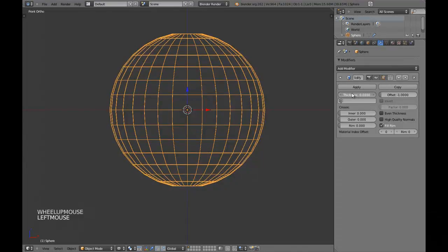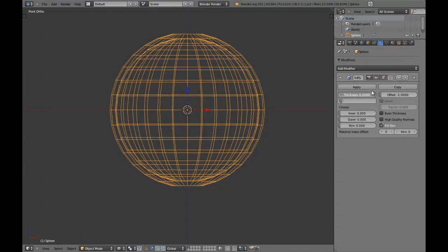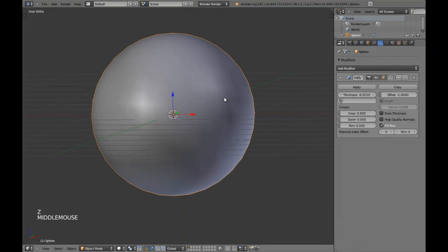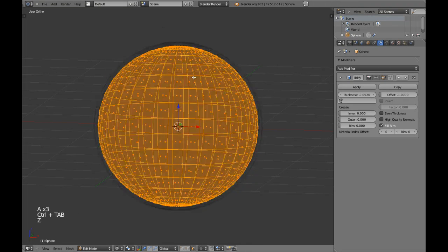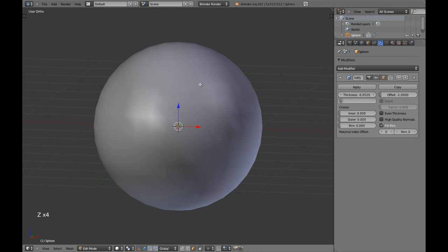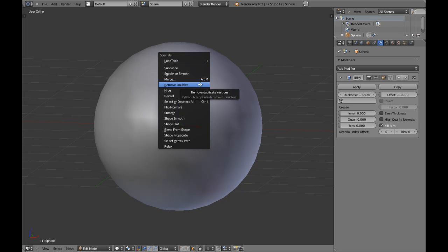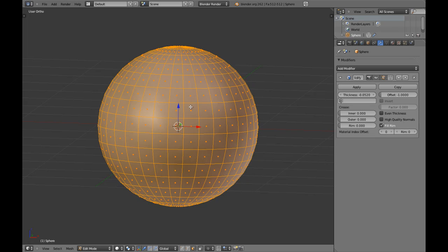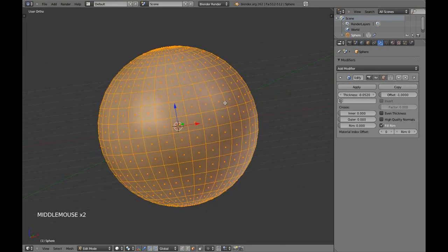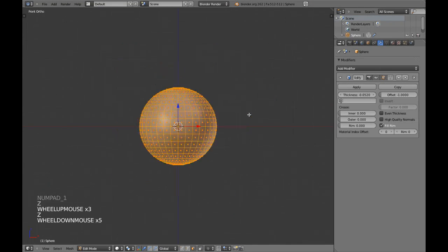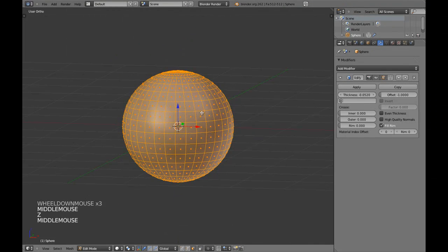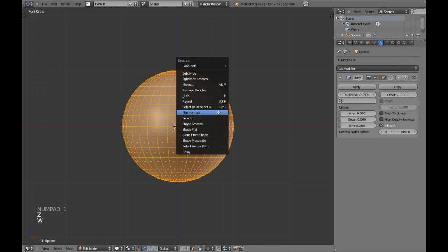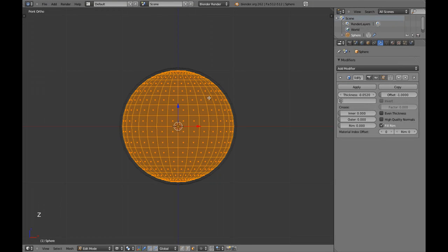easy to use. For example, I told you that the faces have a direction, and in special options with flip normals, you can change the direction of these faces. So Solidify takes the direction of the faces and just makes thickness from that. I will show you.